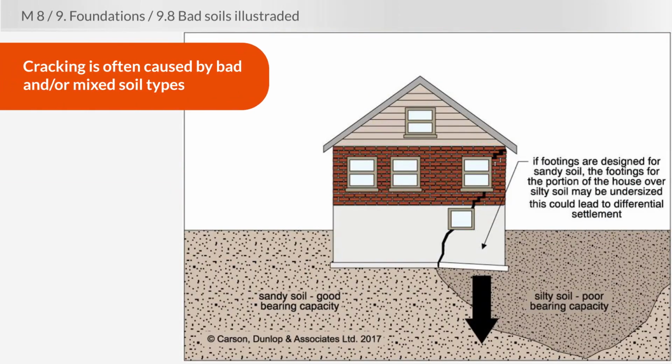Foundation problems are always caused by issues with the soil, whether it's because the home is bearing on unstable soil or because it has been built on clay. Clay causes a lot of trouble for foundations because it shrinks a lot when it dries out, and it expands a lot when it gets wet. So when you have a period of a lot of rainfall in an area with a lot of clay, that clay can expand to the point where it puts a lot of pressure on the foundation walls.